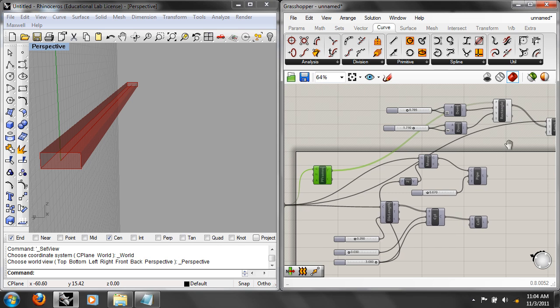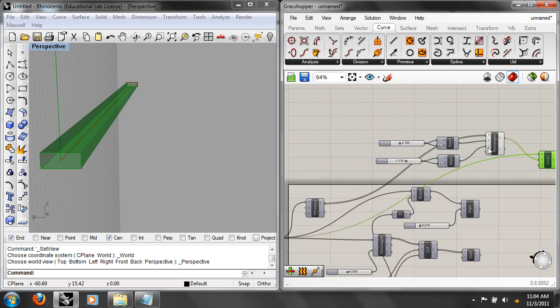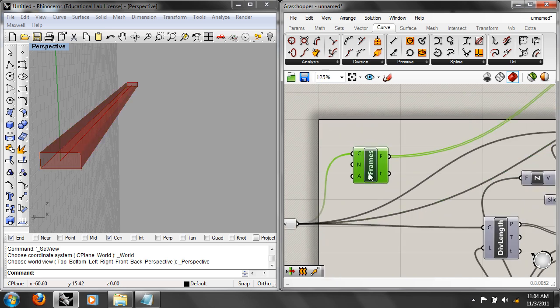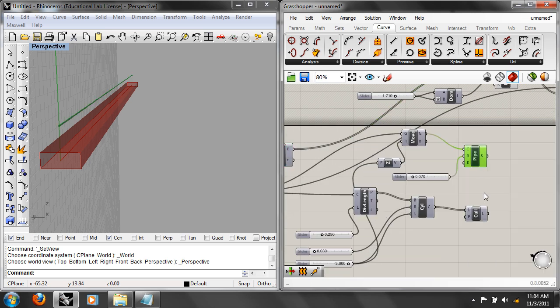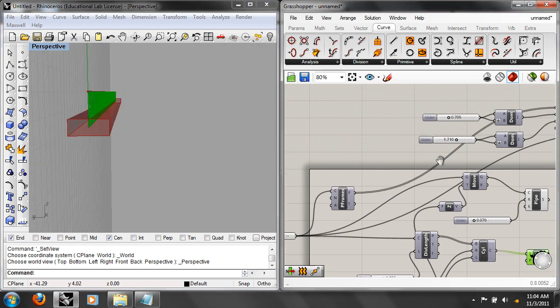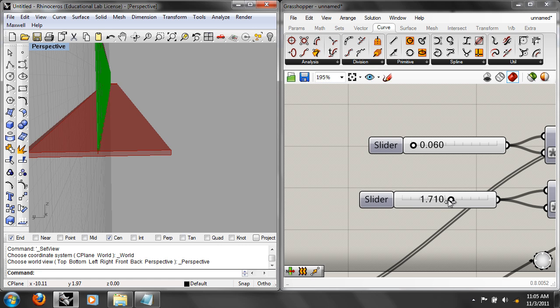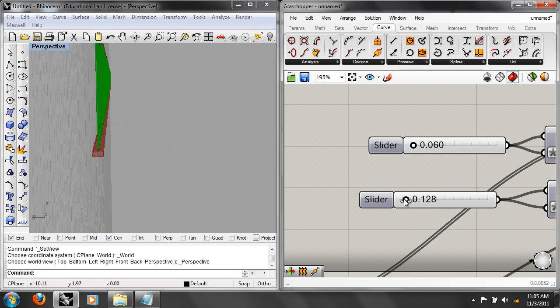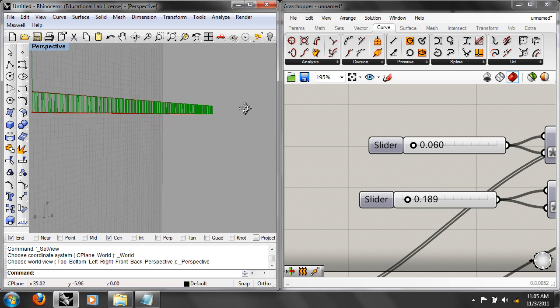Okay, so again, to backtrack, we wanted a sweep, and that requires a rail, which we have, it's easy, and then the sections, which need to be aligned on the rail, and we aligned our rectangles by using the perpendicular frames, which are taken from the curve, and that gives us our section. Now let's go back and turn on our stuff, and we'll see how horribly off scale we are. Yeah, it's ridiculous. So let's go in, and let's parametrically alter our section to be more conducive. Okay, so now you've got that section. So now you've got different, more intelligent sections. Okay.